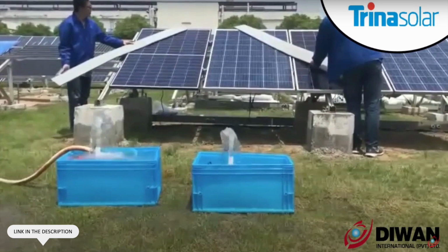Now the guys try a different kind of shading, this time a diagonal shading near the top of both panels. You can see that the half cell panel performs slightly better than the full cell panel. Even with hard shading on 2 of the 6 substrings of the half cell panel, it is still operating at half power, which again is in line with what we would expect.